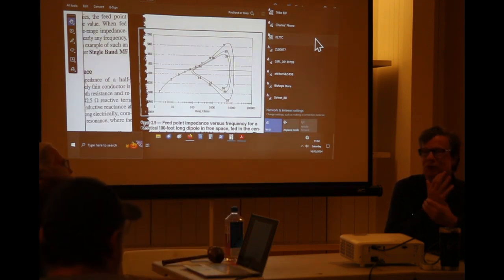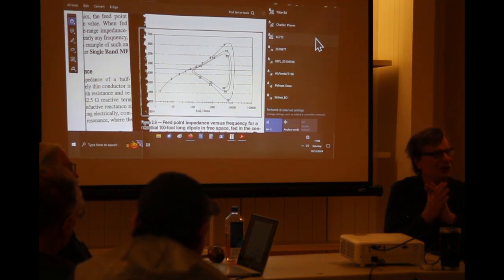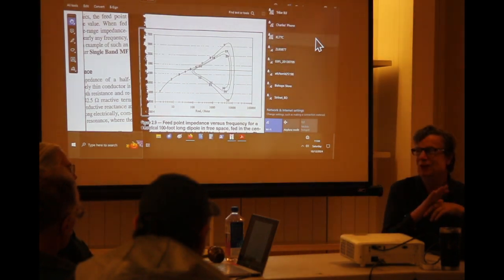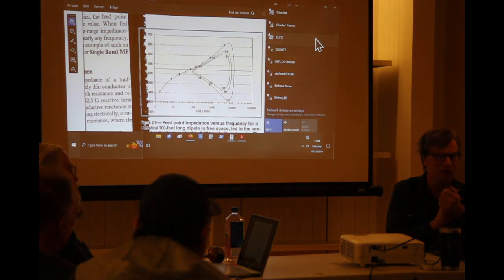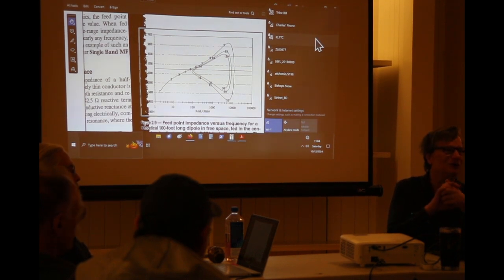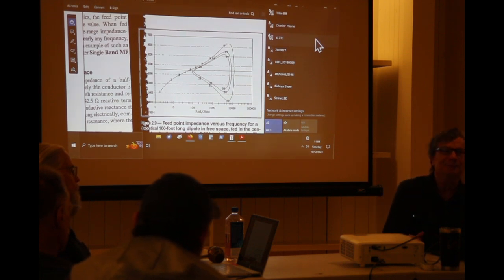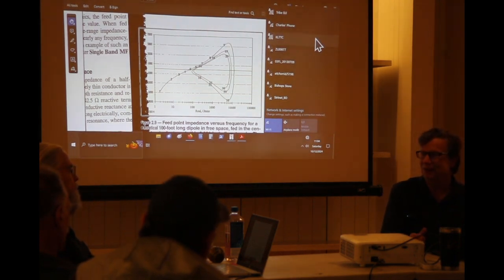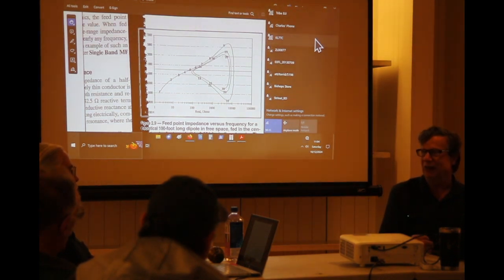Now, part of the reason is you're feeding an antenna at the end, right? And what do we know about the end of any wire when you're doing an antenna? It's going to be very high voltage, right? Very high impedance, very high voltage, okay? It's not going to match 50 ohms. So what do we normally need to add to an end-fed horizontal wire? A transformer. Now, what does a transformer do? It changes the impedance, okay? However, as we will show, it does absolutely nothing to fix the reactance.